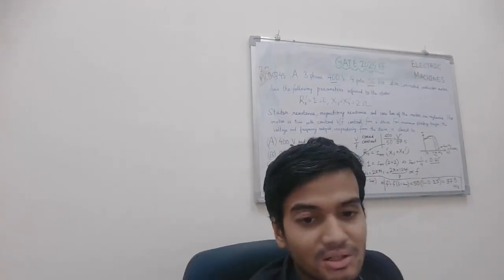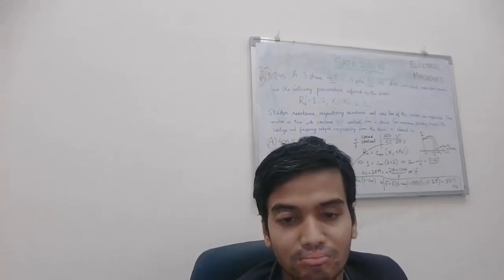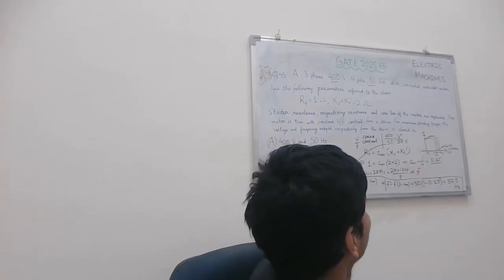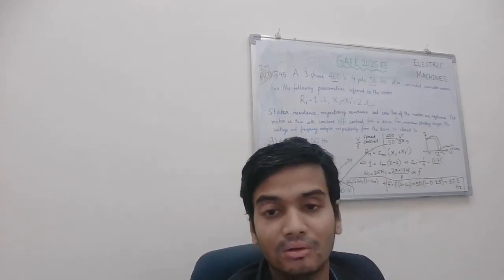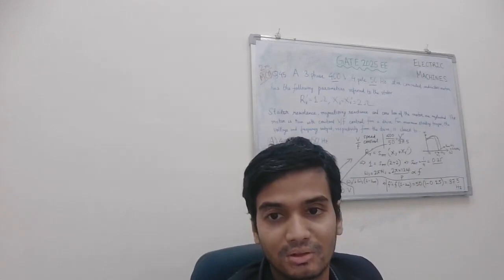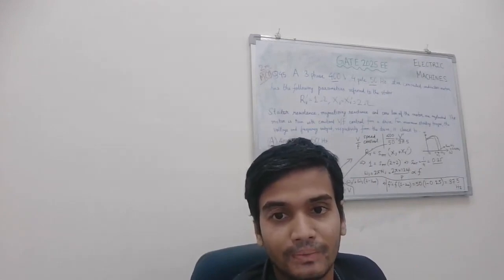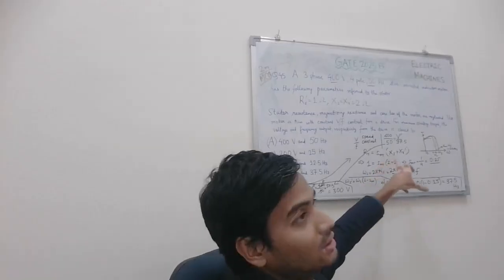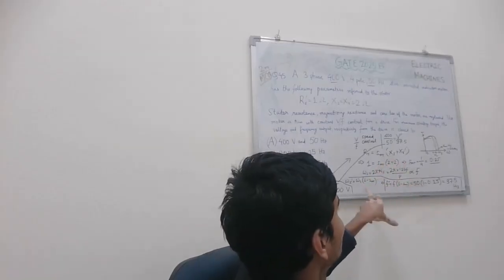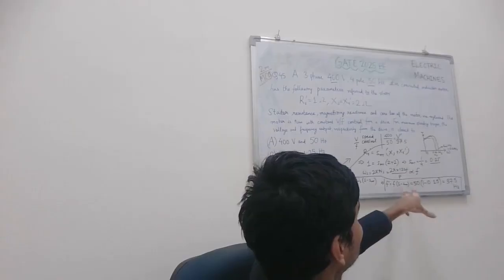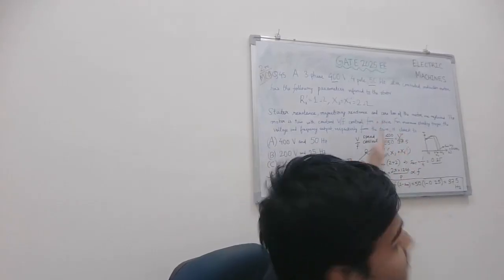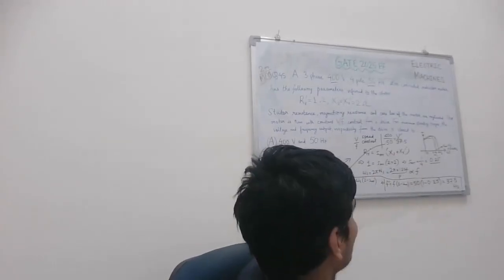To solve the question very simply, we used the basic concept of the torque-speed curves and the V by F control method for induction motors. By finding the slip at maximum torque, we found the required frequency for maximum starting torque, and by maintaining V by F constant, we found the corresponding voltage.